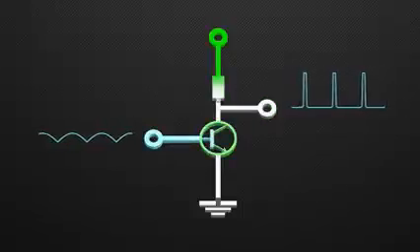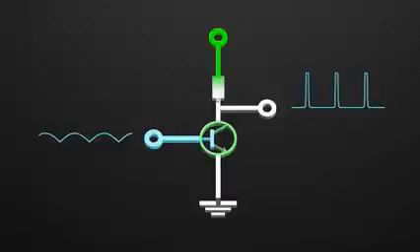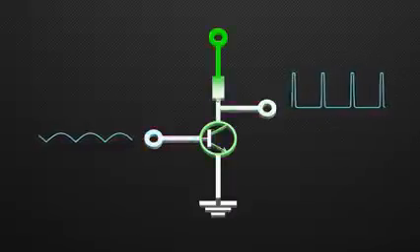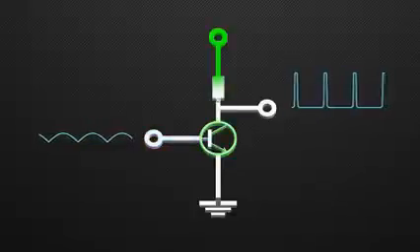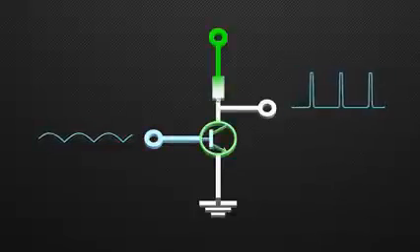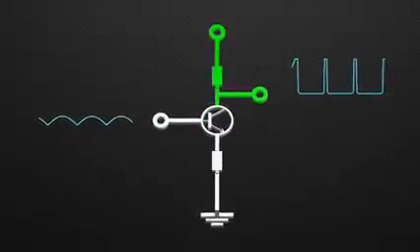The output has a phase shift of 180 degrees. But, the waveform looks distorted, because the gain of the transistor is very high, and it is getting saturated. To limit the gain, we need to provide feedback. Hence, we add a resistor between the emitter and the ground.